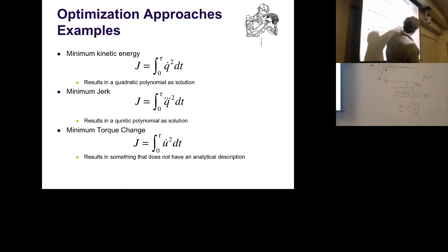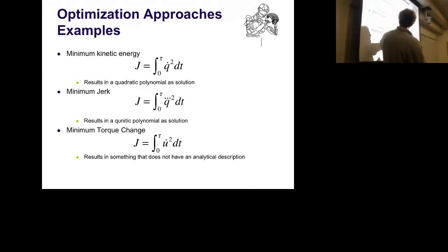Interesting, if you optimize the third derivative squared, that is the change of acceleration, which is also called jerk for some bizarre reason. And so then this entire criteria is called the minimum jerk criterion, which is sometimes good to optimize for all situations in life. So you want to change acceleration as little as possible, which creates essentially a smoothness constraint. And that, as optimal solution, has the quintic or fifth order polynomial. So that's what I showed you before.